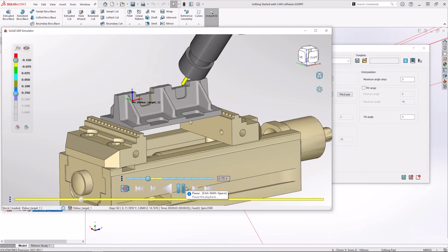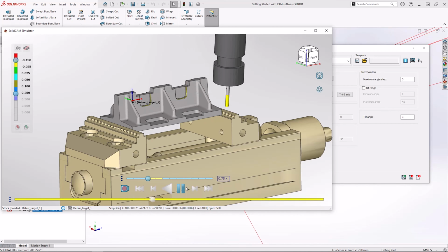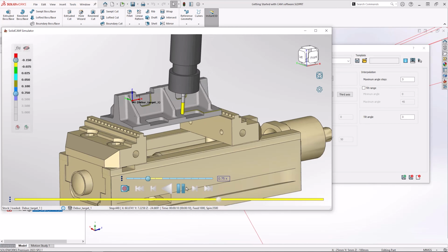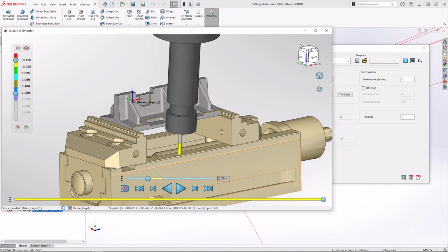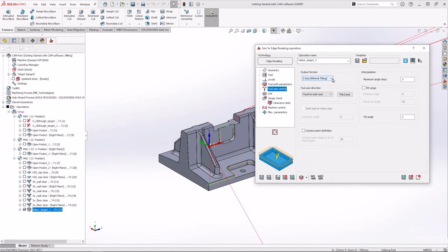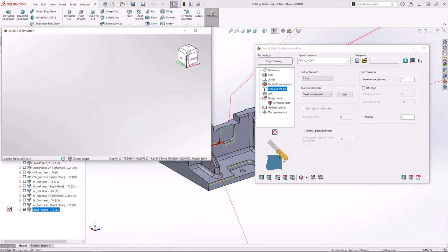Again, upon reviewing these toolpaths, we can see the 4+1 auto tilt and the 5-axis minimal tilting can give similar results, but this depends on your machine and your part, and sometimes one may just edge out slightly, giving you a slightly better finish. The main thing is there's multiple options for you to choose from, as and when you need them. Finally, let's move back to full 5-axis motion, like we had originally. Let's review that again, just to see where the differences are.